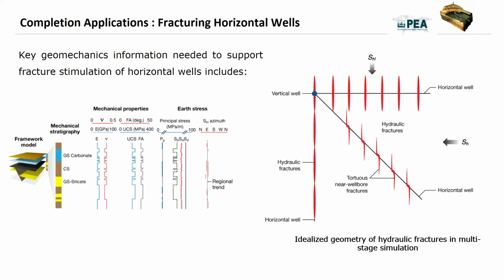So in shale gas production, to achieve hydraulic fracturing of these soils, reservoir optimization requires knowledge of all these stress profiles, and also the knowledge of the stress orientation of the wells that are drilled and how to be fractured. So this calls for careful planning, data acquisition, and fracture design for horizontal hydraulic fracturing.